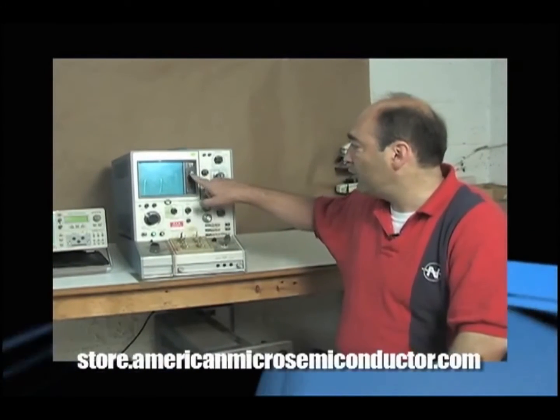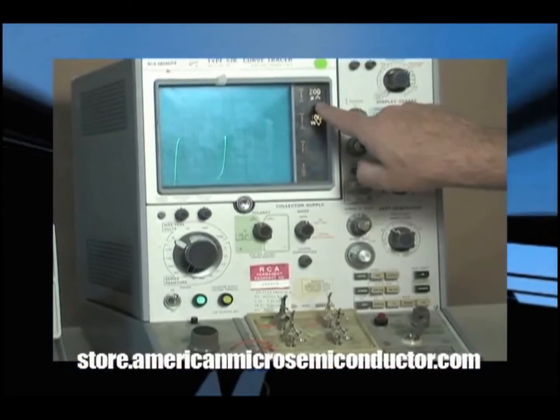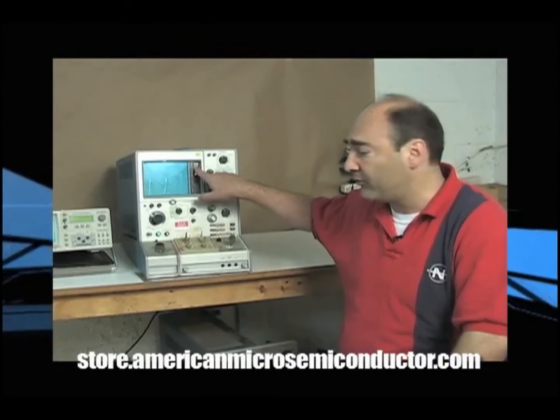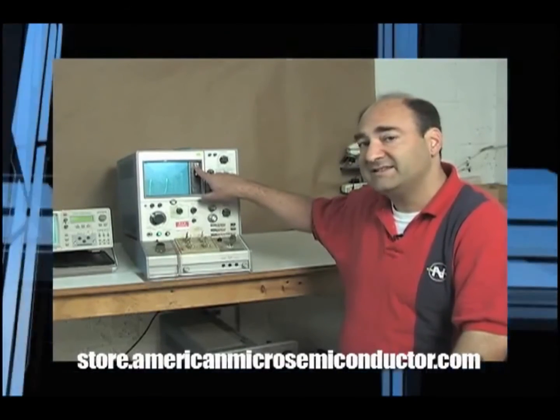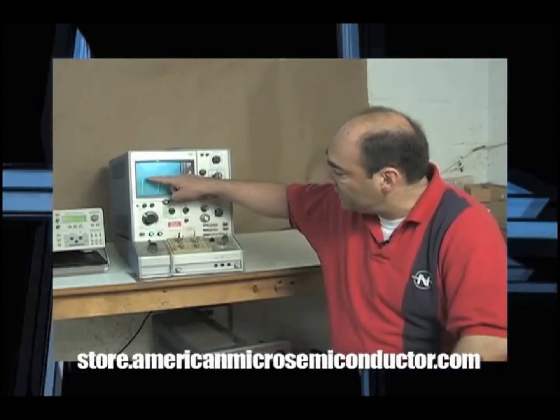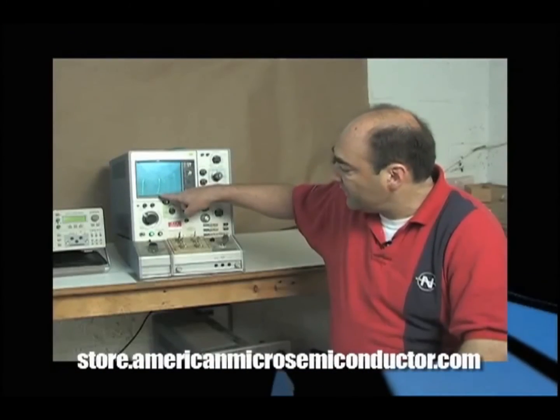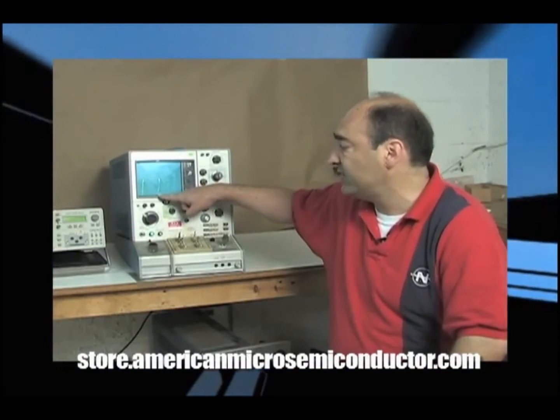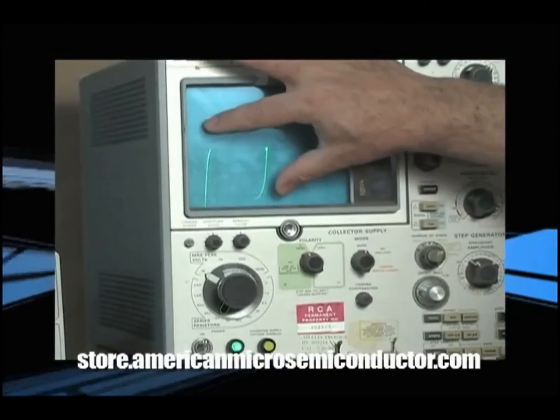If you look up here, we're actually looking at 200 microamps as being the maximum current that this is allowed to operate in. Typically, we want to be less than that. One of the other key characteristics of a tunnel diode is that you want to be looking at what might be referred to as your peak current. This is your peak current up here. Likewise, what we have is what we call a valley current.